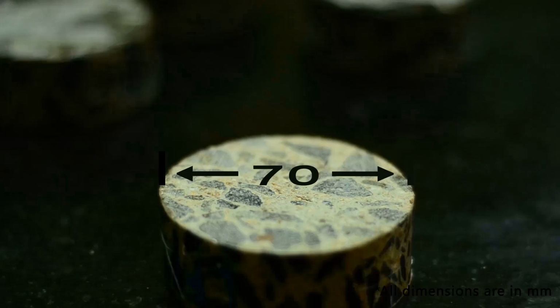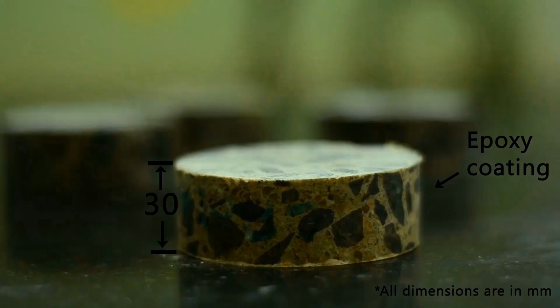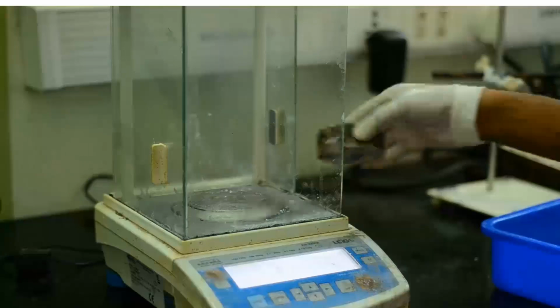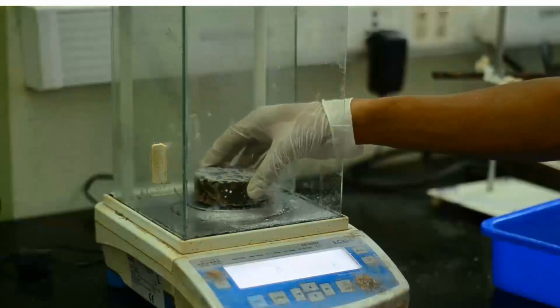Now let us move on to the procedure. First, measure and record the diameter and thickness of the concrete disc specimens. Then, record the initial mass of each specimen.